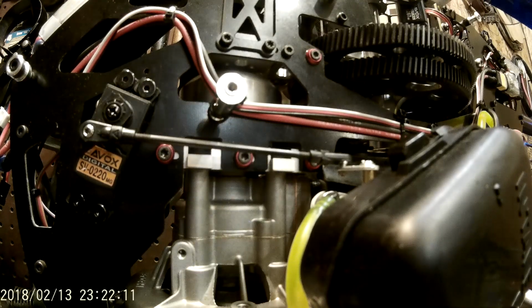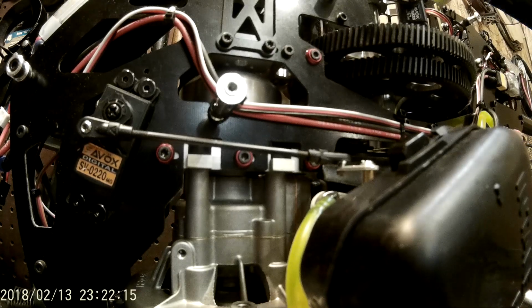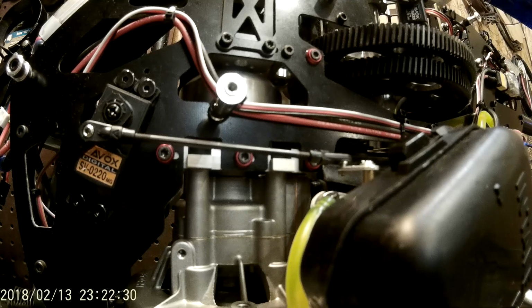And go to the RC radio and disarm it, and that will move the throttle to the closed position and stop the engine. And then if it was idling too fast, adjust that RSC idle up or down a little bit. If it wasn't idling fast enough and wanted to quit, adjust the RSC idle up a little bit. So we'll arm it. There's your idle position. The engine can be started.